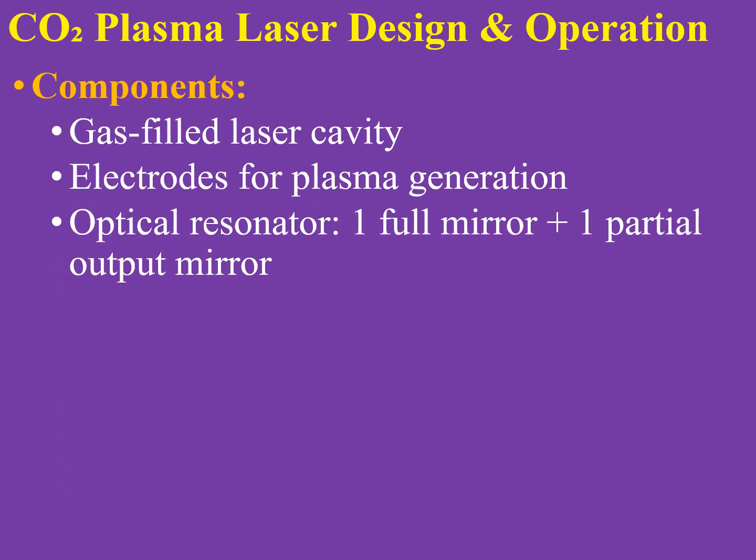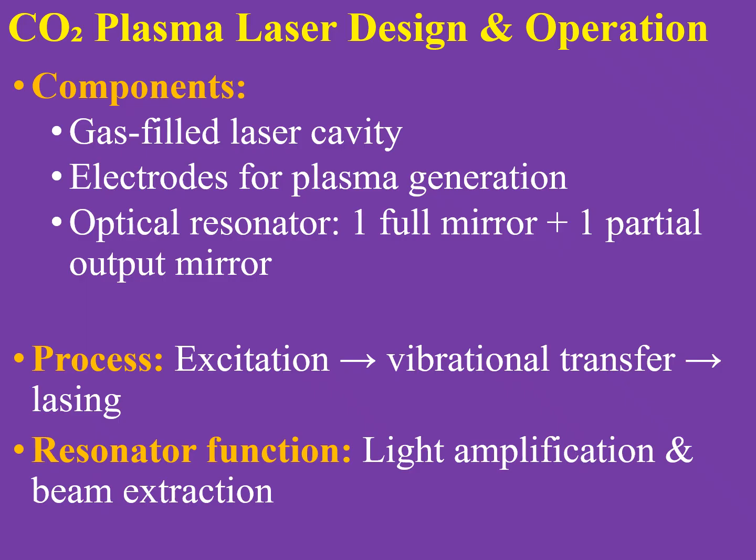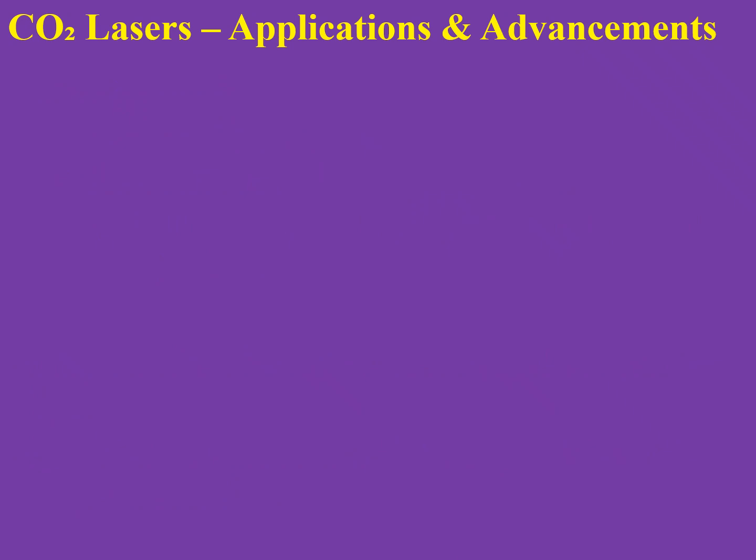About their design and operation, their components mainly include a gas-filled laser cavity, electrodes for plasma generation, and optical resonators, which comprise one full mirror and one partial output mirror. As I have already told you, the process is based on electronic excitation of nitrogen, which is followed by vibrational energy transition to the CO2 and finally lasing. The resonator function is based on light amplification and beam extraction.